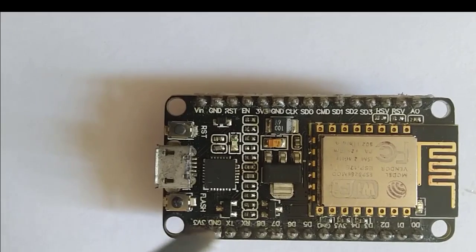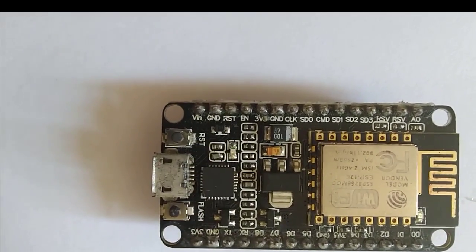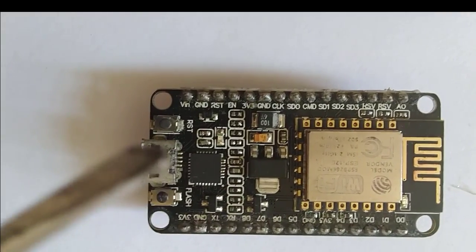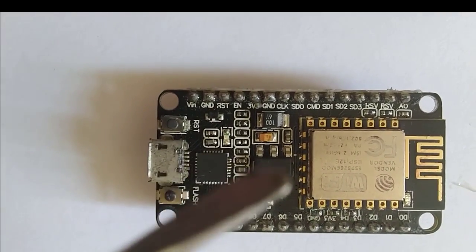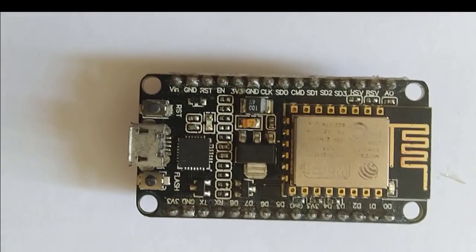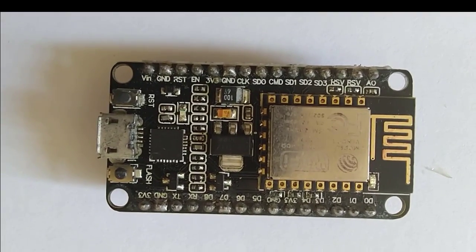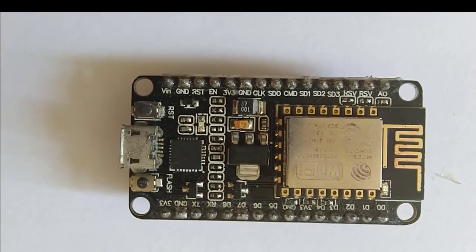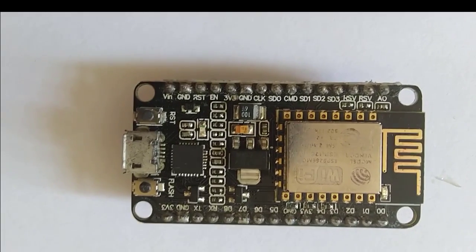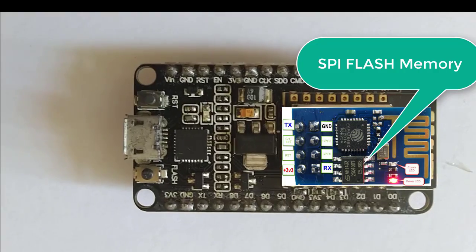I2C is inter-integrated circuit. It also has analog to digital conversion, serial peripheral interface, that is SPI serial communication protocol, UART, and pulse width modulation. And this ESP8266 has a CPU clock speed of 80 MHz and it can also reach up to 160 MHz, and it also has static random access memory and read-only memory, and it also has external SPI flash.